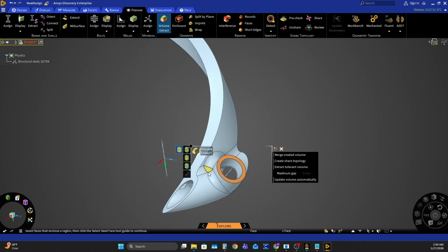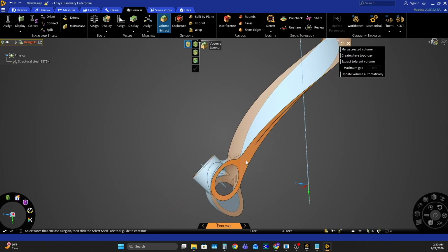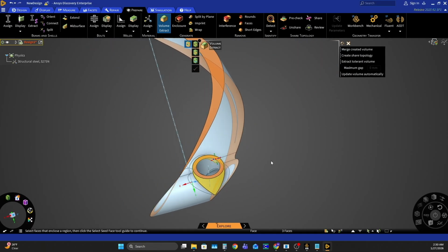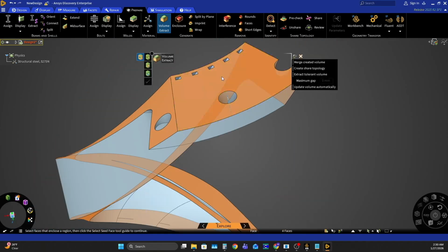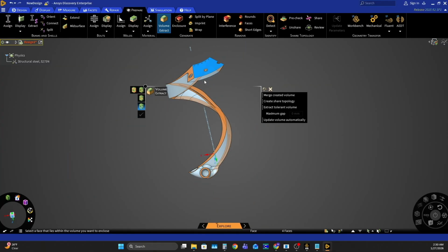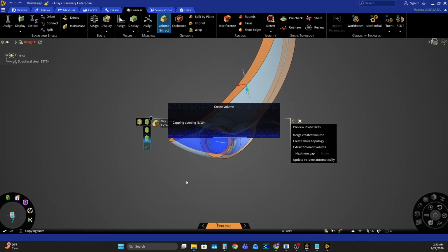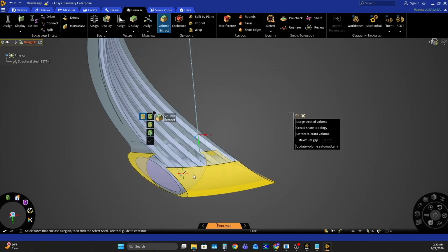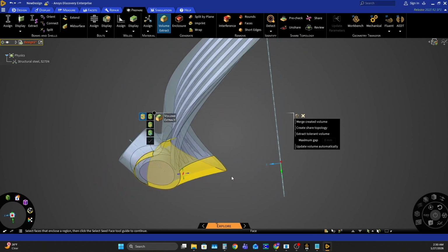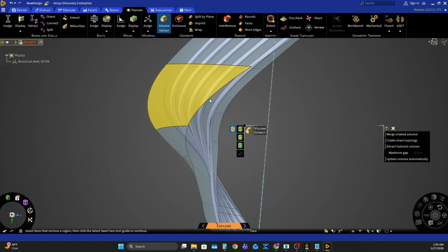So we're going to select the inlet to the annulus, both sides of the cutouts, and then the top flange. And then after that, we're going to come over here and select an interior face of the enclosed volume, and then we can select create. So now we can see the volume that has been created here. I would inspect this to make sure that there's nothing funny going on or nothing incorrect.